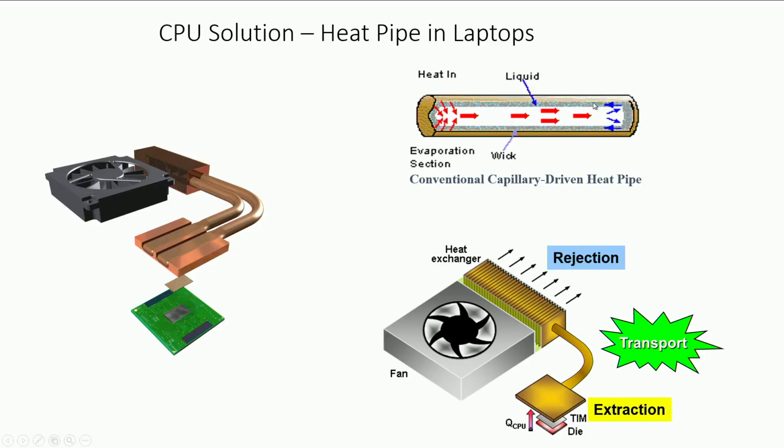What is the material of the wick? That depends. Sometimes it is sintered copper, sometimes it is fibrous materials as well. Many of the manufacturers keep it a trade secret. I can send you some examples that I do not have in the slide. By the way, when you go to very small dimensions, which are also called micro heat pipes, many times it is not a wick anymore, because the nooks and corners themselves provide the capillary action, and sometimes small channels and grooves cut along the internal wall provide it.